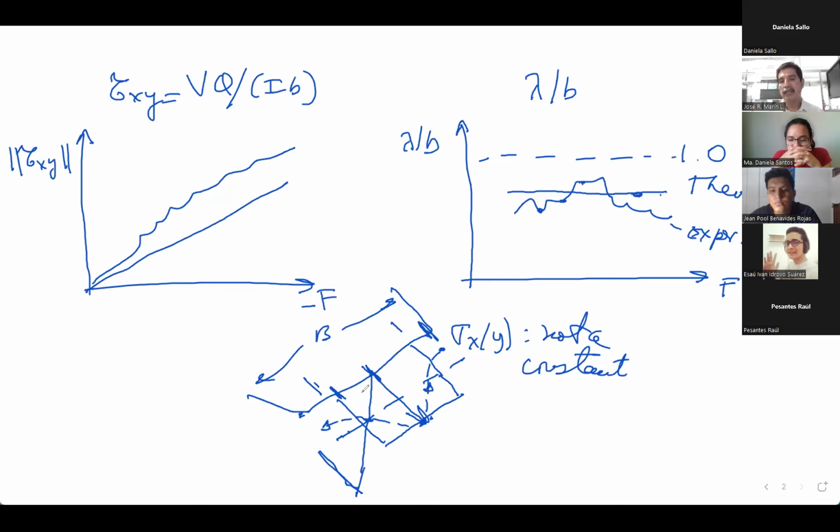So you don't need to calculate sigma. What I'm asking you, this is just values that you can obtain using the epsilons that you measure. So this value here is not calculated, it's measured, because you take the strain multiplied by the Young modulus and you obtain that.